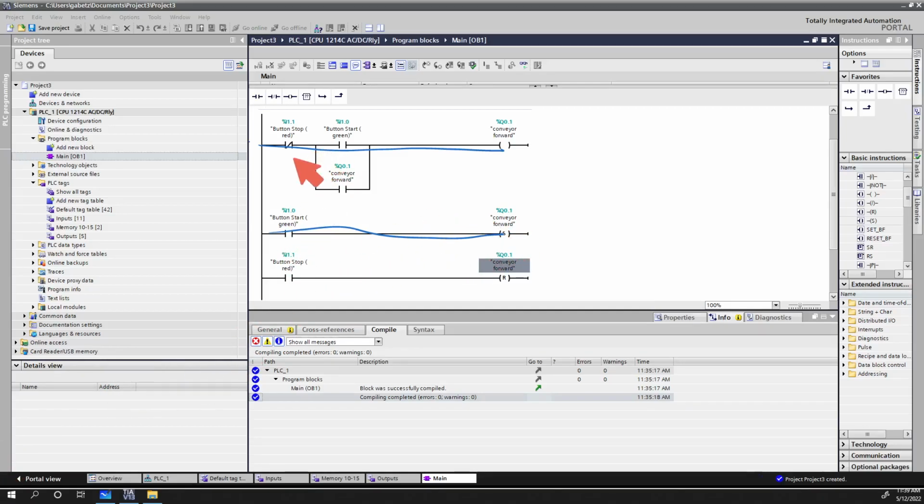And up here, after the first run, or loop 2, 3, 4, 5, whatever, power flows down here. Even if this isn't running, like we'd get to here and we'd stop, but because this is already on, it would stay on. Now, when you press that stop button, at that point, power only gets to here up here, and it would stop. So nothing past it, so that turns the output off.